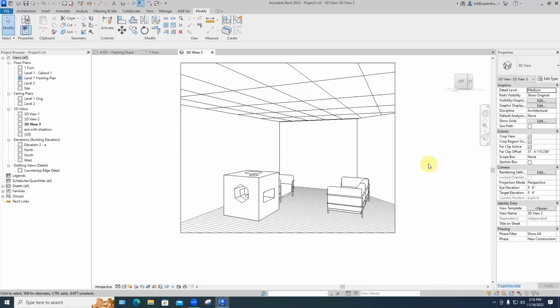I was working on a hospital project for an Air Force medical base, and I was basically modeling all the medical equipment they had to put in there to be sure that the different pieces of equipment wouldn't interfere with each other. And what we did first was make just the first version of almost anything a rectangular cuboid as big as the thing could be, and put that on the wall or on the floor, wherever, to make sure it wasn't going to bang into anything else. And then over the course of time, we come back and refine those and put the dials and whatever on it that it had to have. But you can think of families as something in a continual state of improvement.